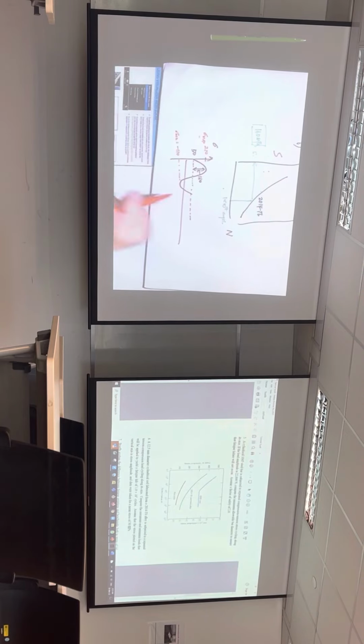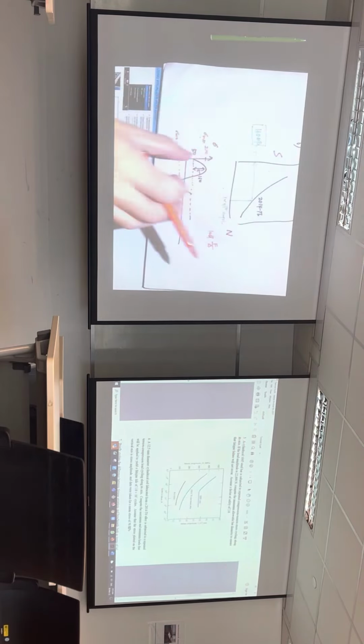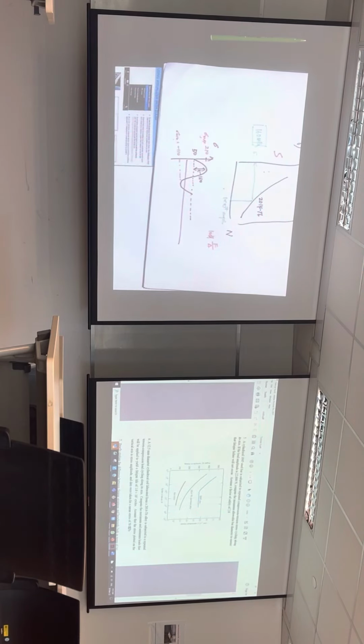Over here, basically what you are trying to do is you're finding the load. Load will be F over A, right? Now you have the stress, you'll be able to find. So this is a simple application of a SN curve, and then knowing this, you will figure out, translating from a cycle that is a book value to actually a design. Actually, I cannot do more than dump X number of load inside the materials.